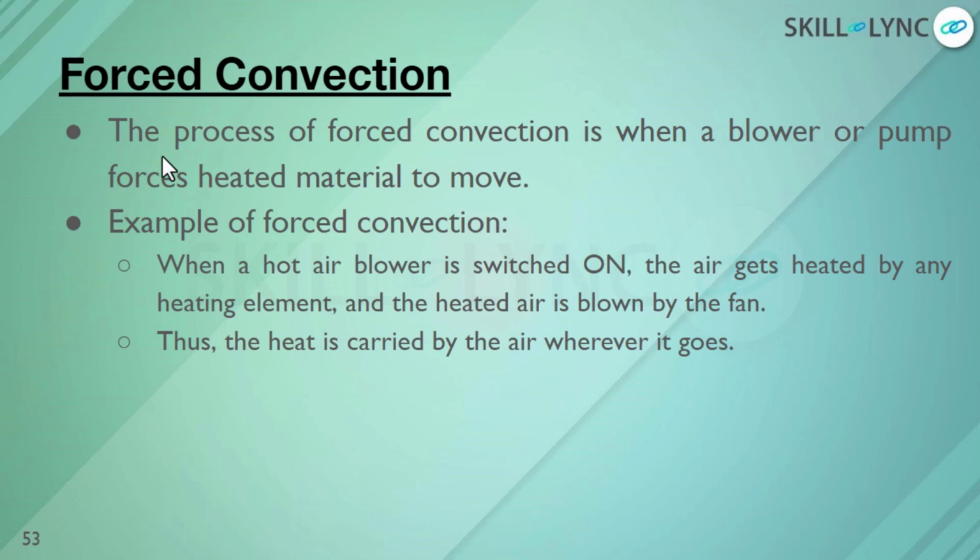The next type of convection we are going to study is forced convection. Forced convection is when a blower or pump forces heated material to move. In natural or free convection, the material moves by itself due to the difference of density. But in forced convection, the heated material is given external power from a blower or pump to make it move.